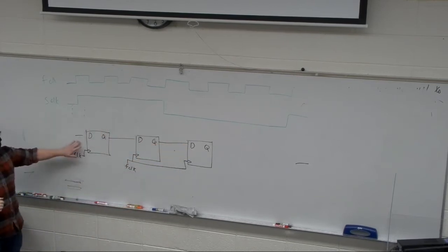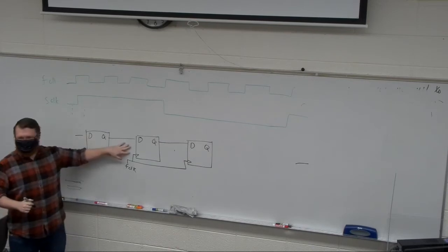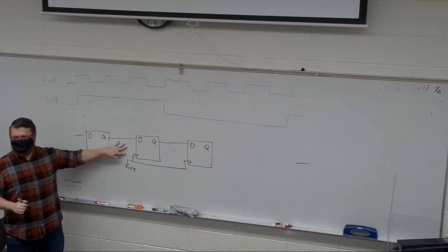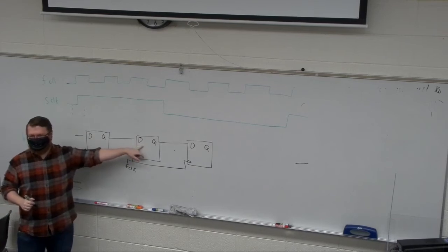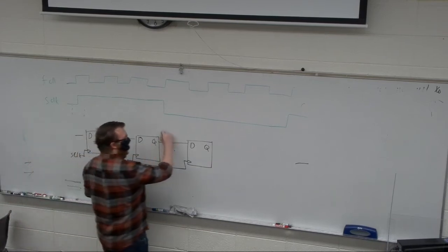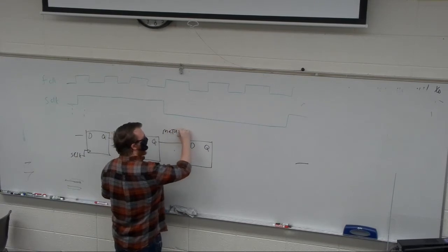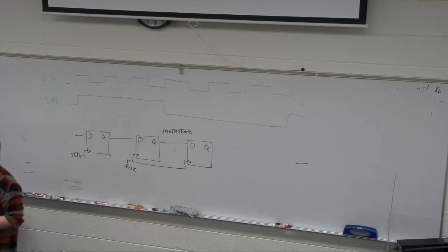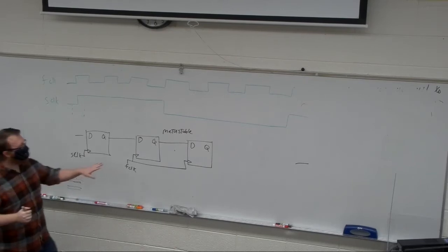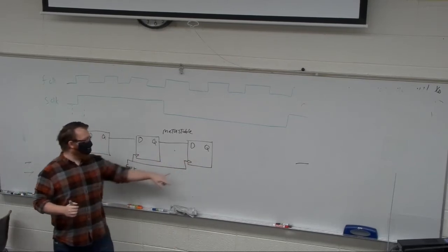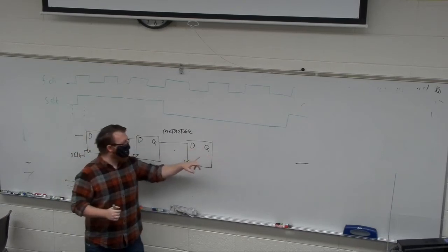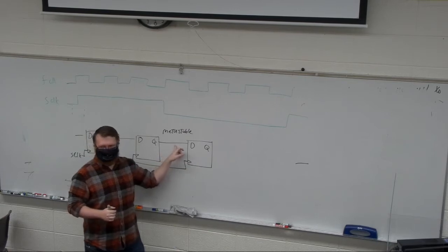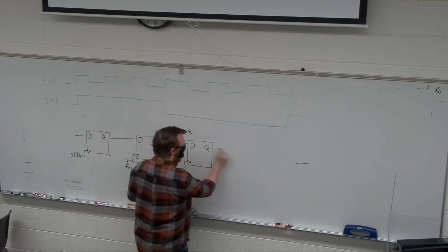All right, we have the slow clock and the slow clock domain. It updates. We know that there might be a race condition at this output, right? When this updates versus when this updates, that creates a region of, flashback to this, metastability. And then when we clock in again on this fast clock, we're no longer metastable. So we have an output, because this one kind of just doesn't know what it is. This one has to, because it's in the same clock domain.